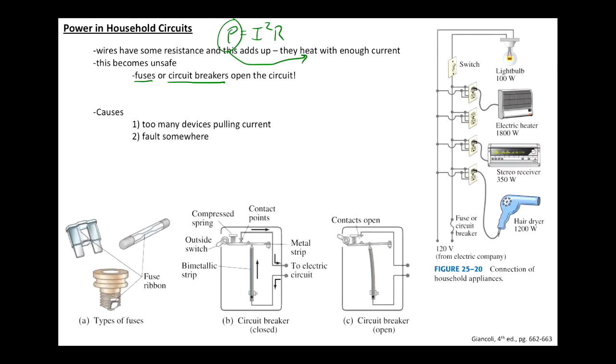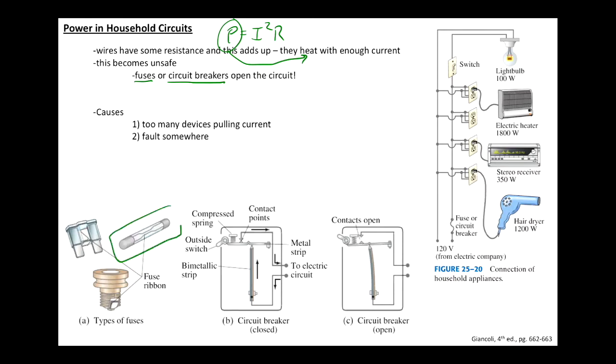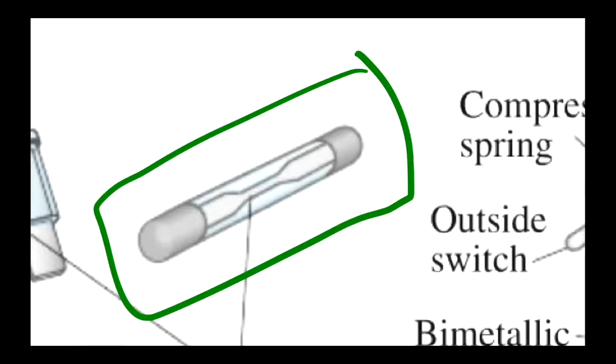And these are some clever devices, specifically the fuse, which you can see here. It's literally just something you put in the circuit that has a piece of metal that, if it heats up a certain amount, just melts. But it's self-contained in some glass, so it doesn't really do any harm. If I zoom in on that a little bit, you can see that metal filament going down the middle. It would melt, and then all of a sudden there's just a break in the circuit, and physically nothing can flow anymore. It's kind of ingenious, kind of nice, but of course it's destructive. Once that melts, you've got to get a new fuse. You can't just put it back together in some way, okay?